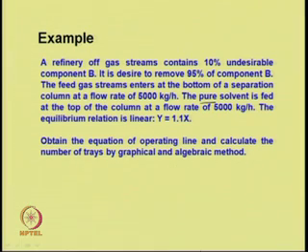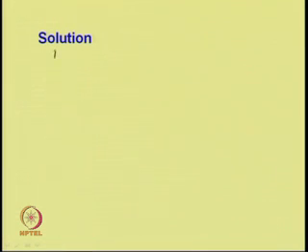So, as we can see, this is a counter current operation and the concentration of solute which is to be removed is given as 10%, and we have to remove 95% of component B which is undesirable, and both the liquid and the gas stream flow rates are given. So, feed concentration is equal to 10%. We can write on solute free basis.